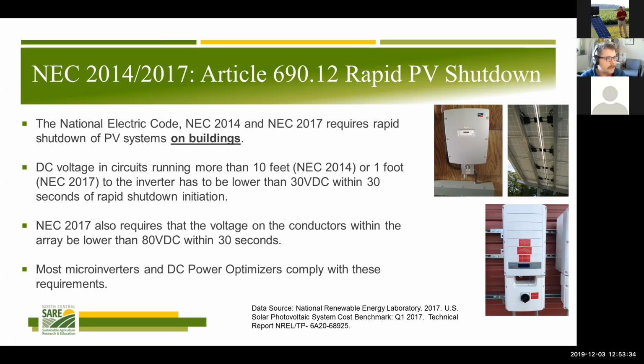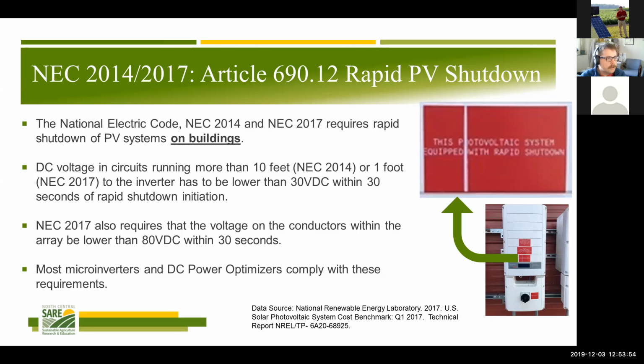So meeting electric code requirements is really good, and that rapid shutdown question is a good one for that. Basically it says for fire safety, we need to be able to shut them down at the panel level, particularly when they're on a roof. So roof mounts need rapid shutdown, ground mounts don't. That's the general answer. It gets a little more complex, but that's the general answer.